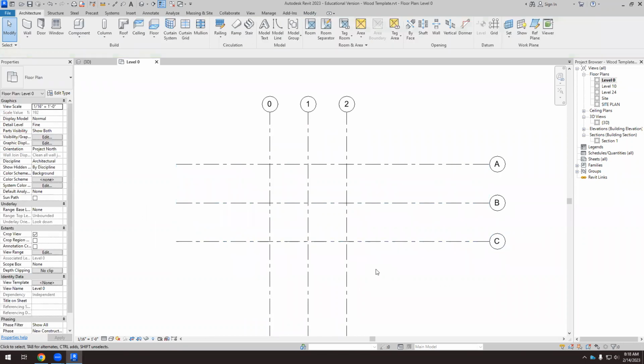And we're going to start from the foundations, and then we will create a structure with columns, beams, and a roof. Foundations are always the same. If we have a basement, we always need a concrete retaining wall, and then we need wall foundations for the walls, and then we need isolated foundations for the columns. If we are working with basements, a basement is always made of concrete, so we don't make a basement with wood. It doesn't make any sense.